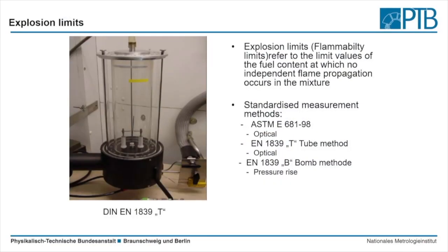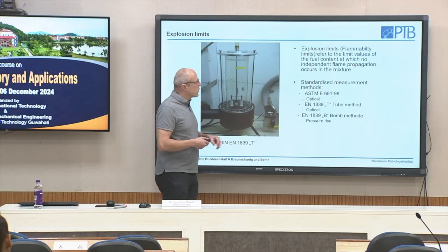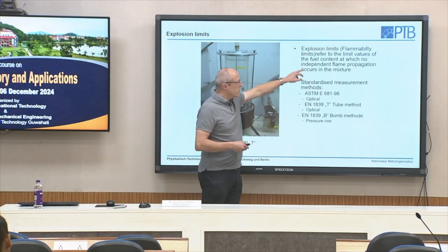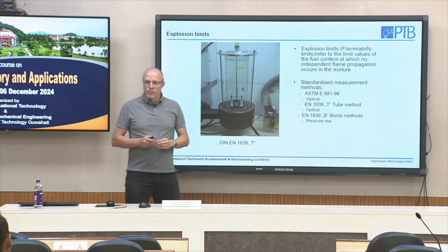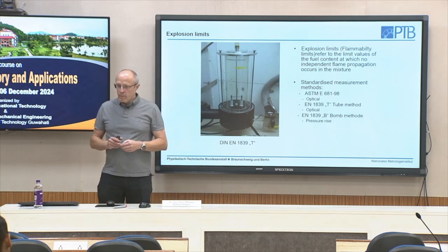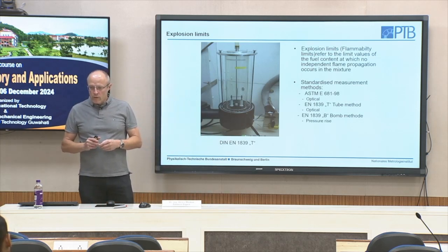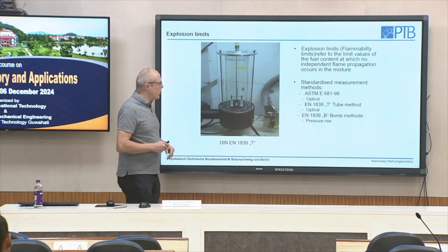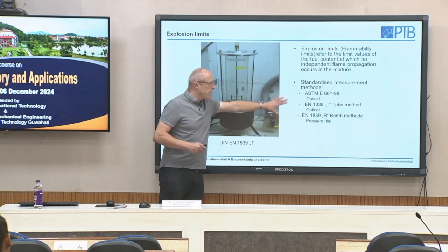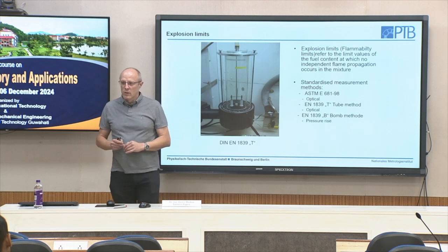So explosion limits, or in the American literature also preferred to use flammability limits. So these are normally the same. They refer to the limit value of the fuel content at which no independent flame propagation occurs in the mixture. This can be determined by different standardized measurement methods.